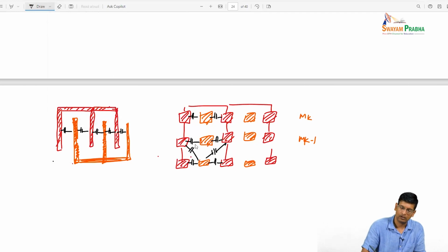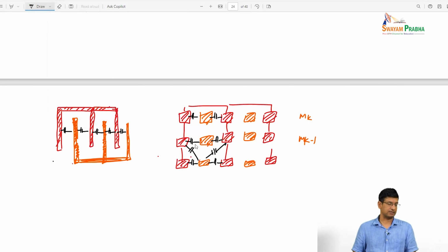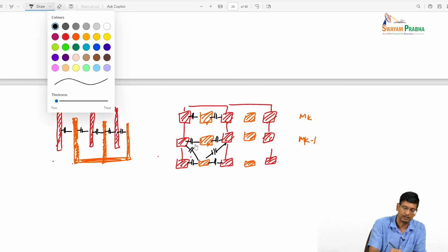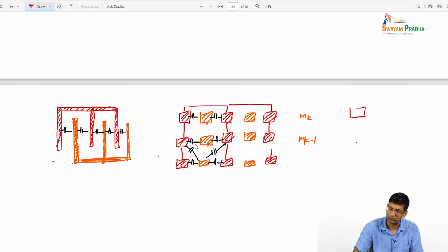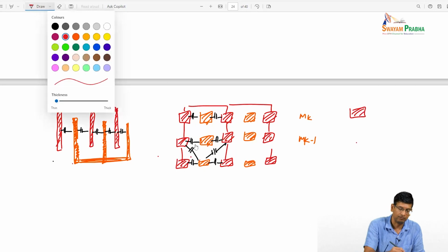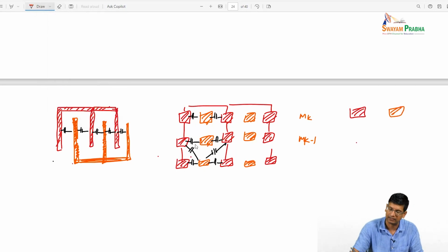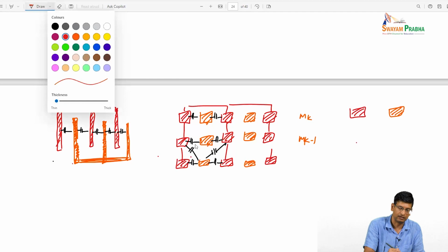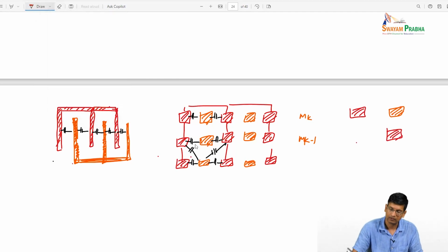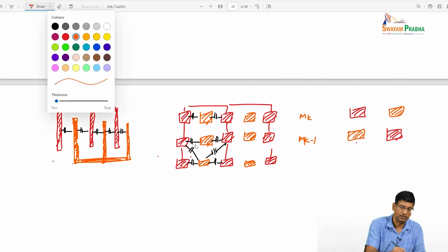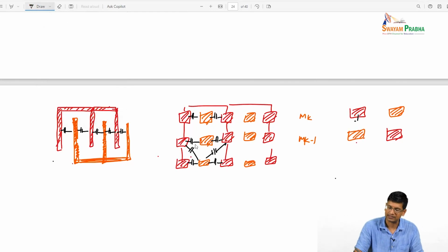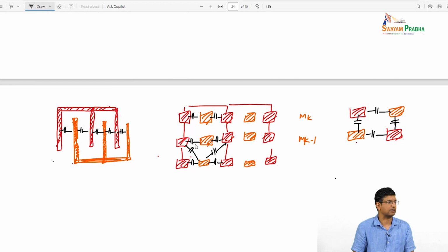Now as soon as you do this, you realize that, hey, I can get even better if I distribute the two layers this way, which is that I make the first layer like this and like this, and then the next metal layer I do this, right? So now I am creating a situation where I have capacitances like so, like so, like so, right? So I'm basically increasing my capacitance density.